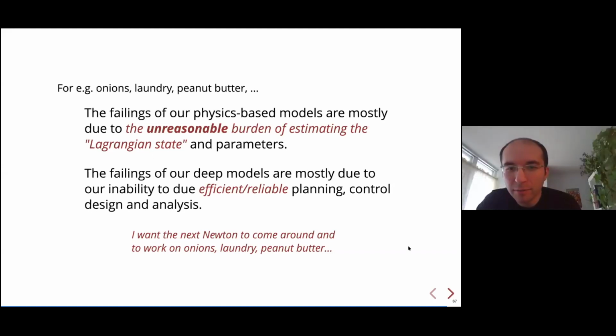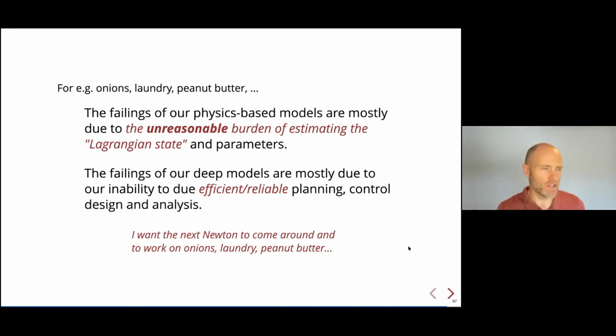All right, Adam Hall asks, first of all, he says your talks are always awesome. And he asks, where are you headed in terms of combining many different sensor modalities to achieve similar robust manipulation? That is such a good question because, yeah, I mean, so we said key points are good for perception. I like to think the nice thing I like about the dense tactile sensors is you can basically think of it as a short range depth sensor in your fingertip, right? So it does fuse right in as just a multi-camera kind of fusion problem in that sense. But at the same time, there's a deeper representational question that we haven't cracked yet about it. You know, what fundamentally do you do differently if you have slip available and you have these other things? So key points I don't think of as the only solution by any means. It's just a stepping stone. But there are probably some really good representations that lie at the intersection to be found.